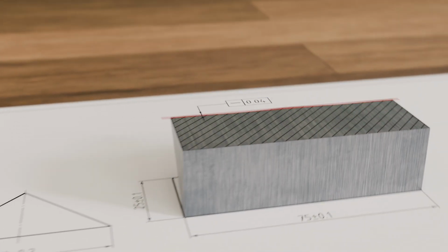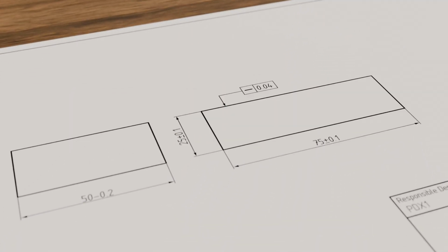Instead of the prism, let us now consider a cuboid-shaped component. In this case, the top surface is not a one-dimensional edge but a two-dimensional surface. This top surface is intended to serve as a support surface for another component and therefore must be as flat as possible. This generally applies to all ceiling surfaces. For this reason, we initially also tolerate the top surface with straightness. However, we will soon see that this is not effective in this case.